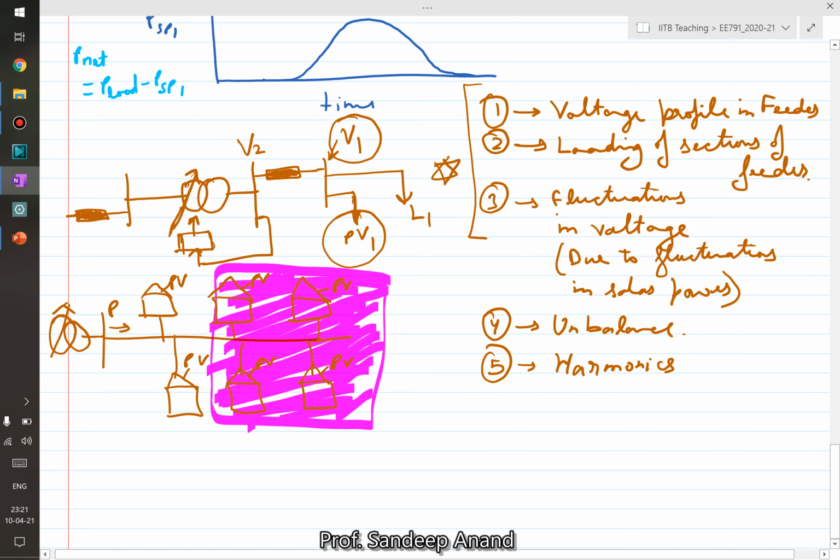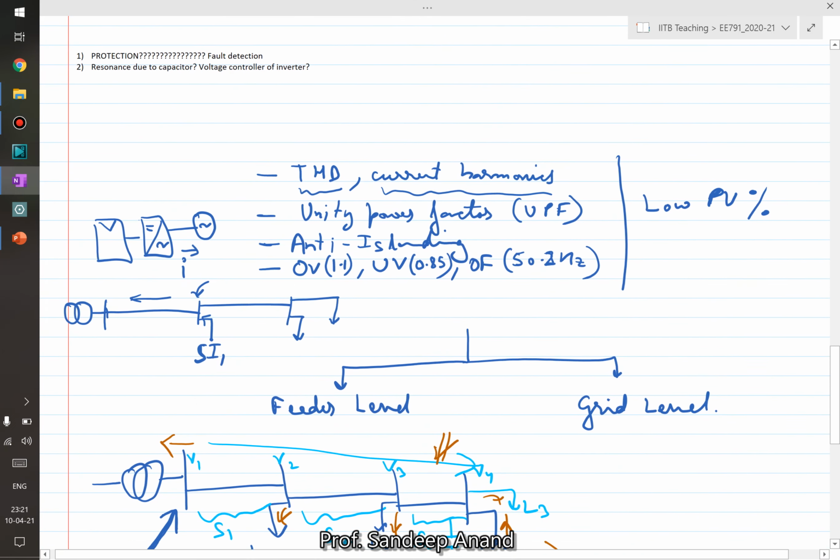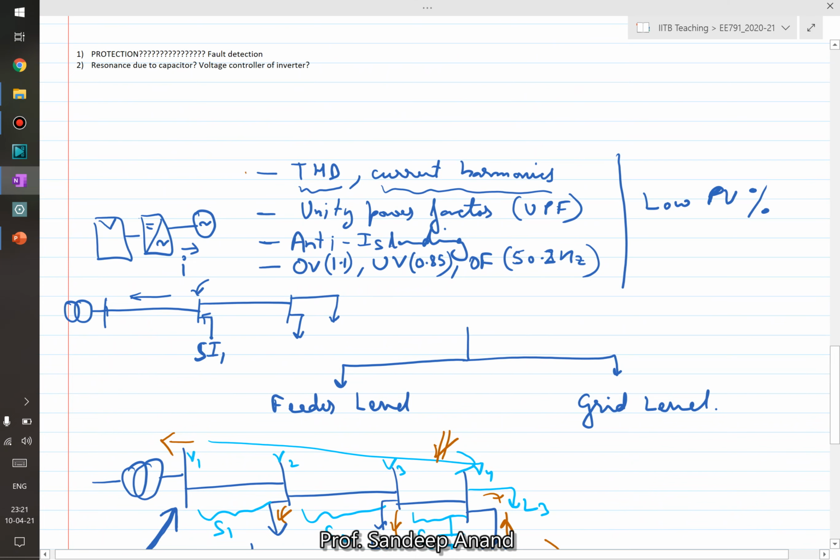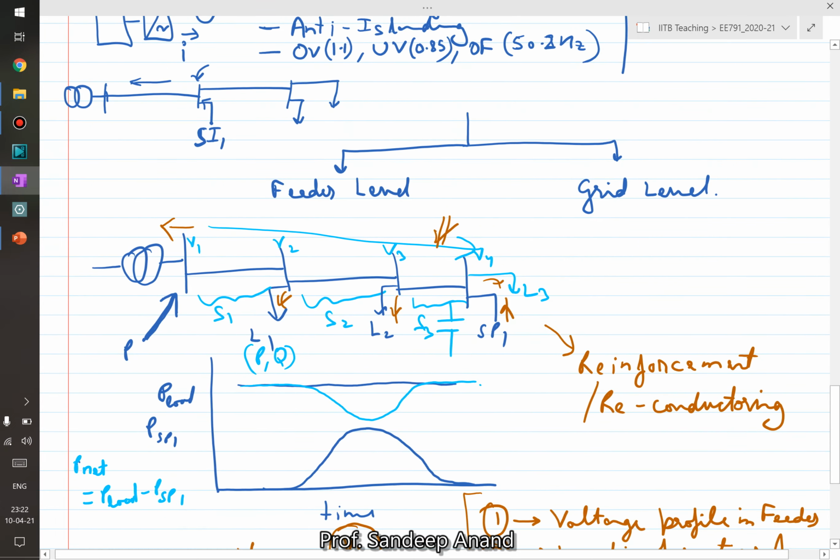Now, if you recall the earlier discussion we had in this video, this was the first thing which people thought of, right? If a power electronic converter is getting connected into the grid, it would create issues in terms of harmonics. So this was already fixed at level 1 itself, saying that the inverter should inject current which has a very low value of total harmonic distortion.